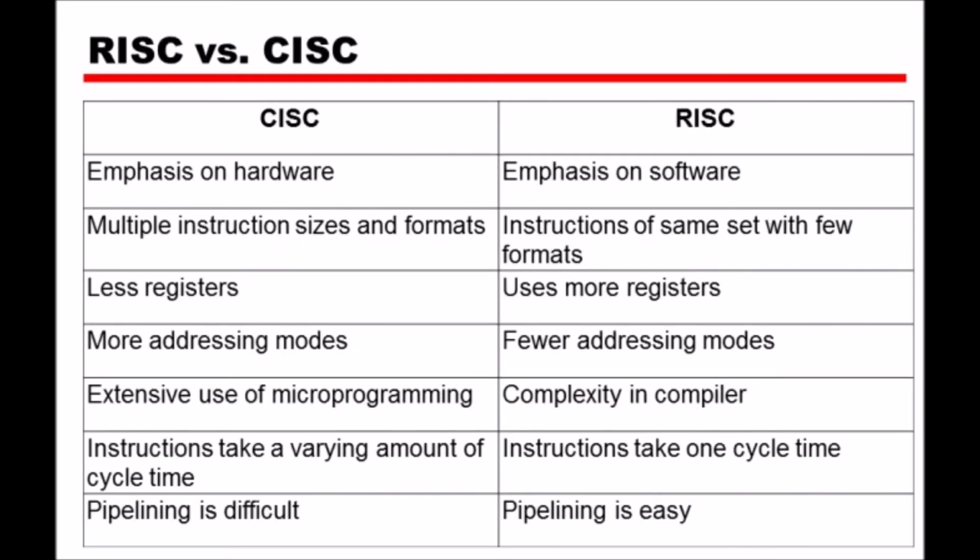MCU processors can be based on differing computational instruction sets, complex or reduced, as in CISC and RISC. In general, CISC has about 80 instructions, while RISC has 30. Also, CISC has more addressing modes, 12 to 24, compared to RISC, 3 to 5. While CISC can be easier and uses memory more efficiently, performance can be worse due to increased clock cycles required to execute instructions.